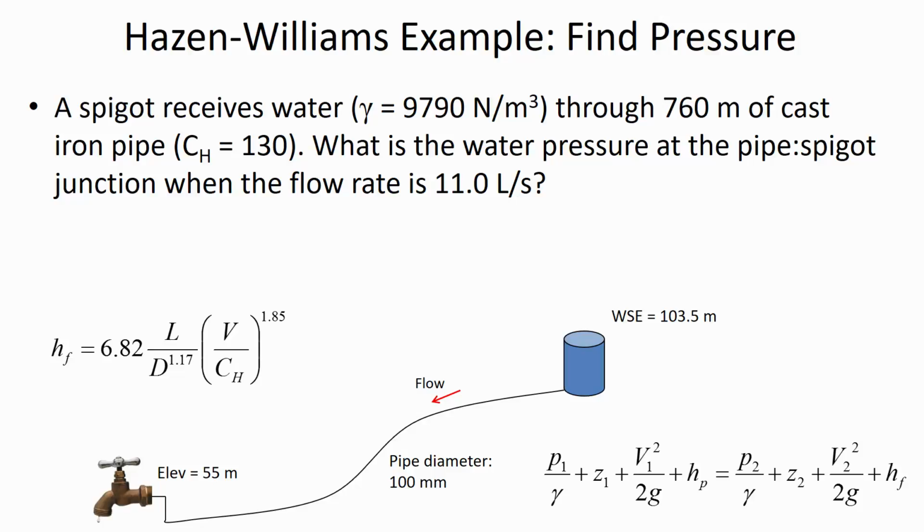But if you take the hose off, then there's zero pressure as the water comes out and is just in contact with the atmosphere. But just on the other side of that valve, now there's water pressure that is available. And so suddenly you're just losing pressure, and the elevation didn't change, and the velocity on one side of the pipe is the same as on the other side of this valve.